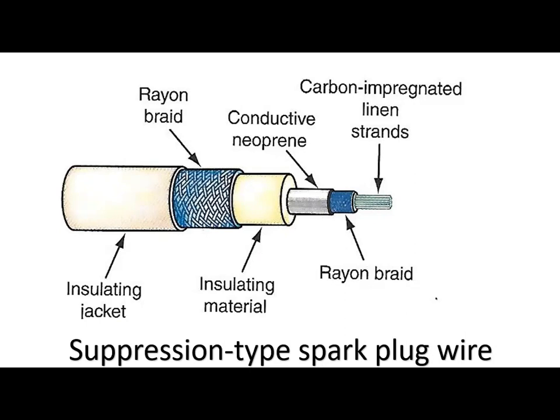Because spark plug wires conduct high voltage, they must have heavy insulation made from Hypalon or silicone. Metal ends on the spark plug cable connect the center conductor to the spark plug terminal and the distributor cap or ignition coil. Most spark plug cables have an outer diameter of approximately 0.312 inch or 8 millimeters.